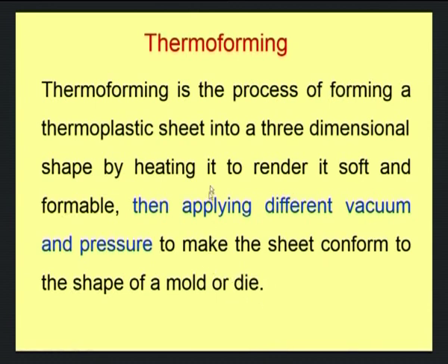That is, as and when the thermoplastic sheet is passed through the mold, a vacuum or a high pressure is injected inside the mold. As a result, the thermoplastic sheet will take the shape of the mold.